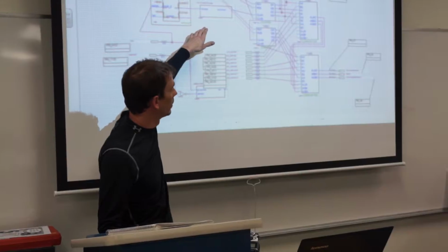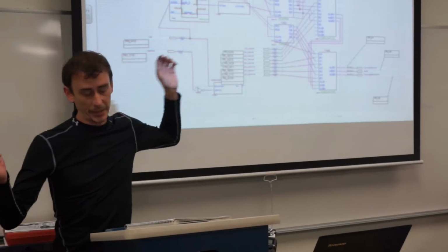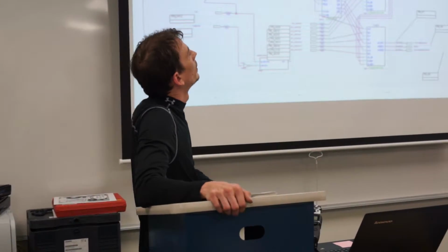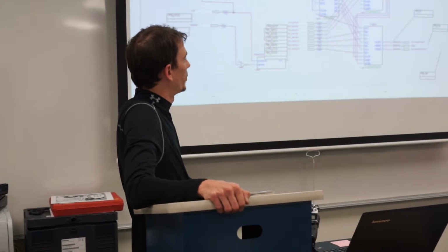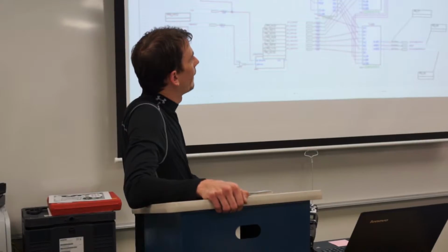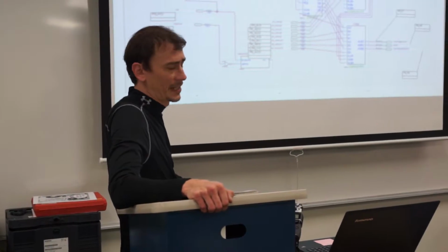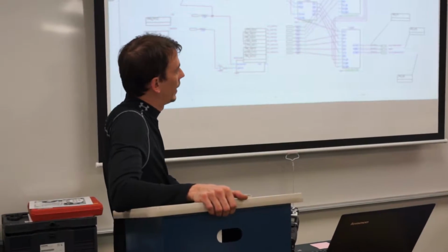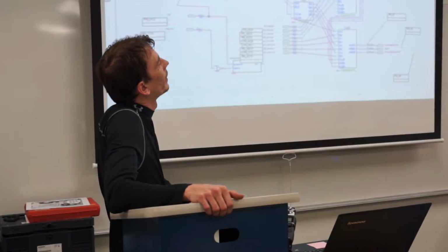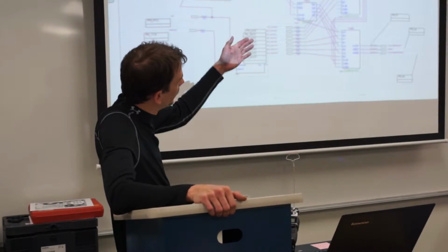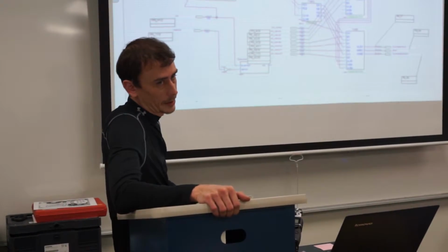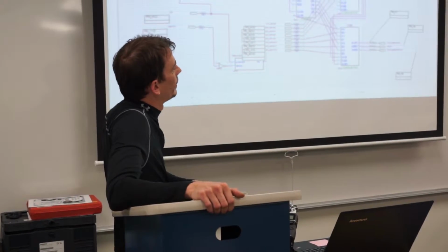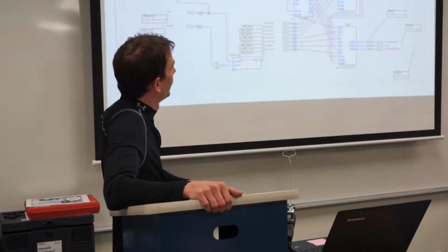Initially, I started down at the 32.768 kilohertz that you guys were using back there for the design, and I'll get into why that clock speed had to change. But there's such a vast parts catalog out there when it comes to selecting these digital components. After I had my 4-bit stuff, I decided just to double it and use multiples of them to get to our 8-bit system, rather than hunting through to find the exact equivalent version in an 8-bit chip. So I just plopped a couple more down there.